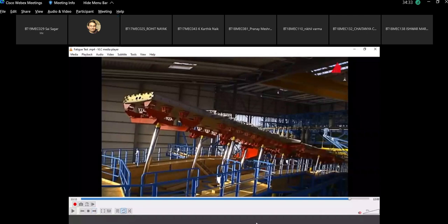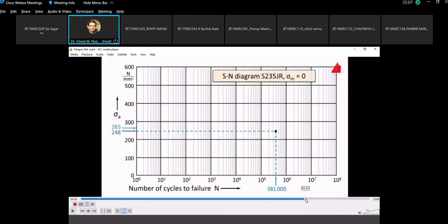So okay, is there any doubt? Last time, for the tensile testing in the UTM machine, the purpose of the test was to find the fracture strength of the material. So we plotted the stress strain curve. While for the fatigue loading, what we are doing is applying a number of cycles of loads. Our aim is to find after how many cycles of loading the material will fracture.